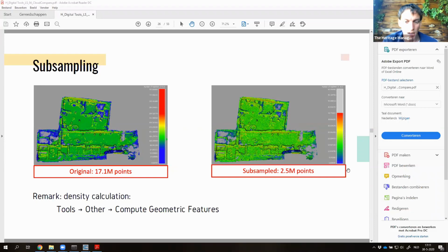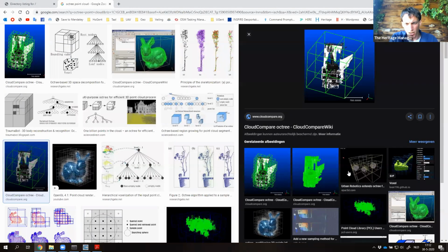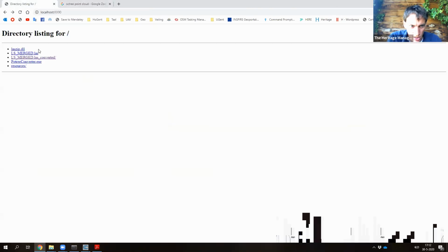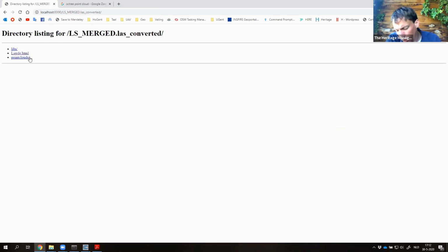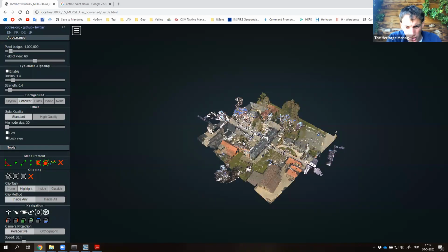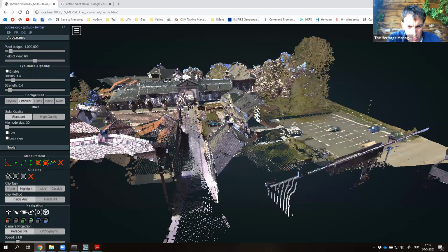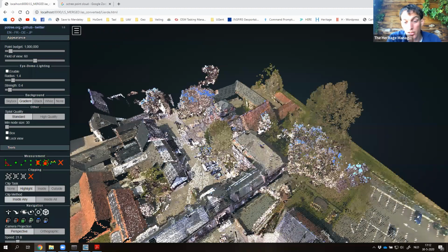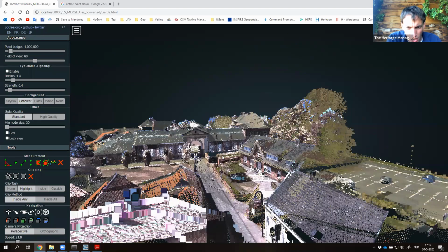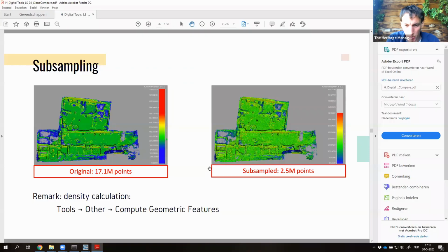I assume that Michele, who will do the guest lecture on Monday, will tell you more about this software. So the step from acquiring the data to having your point cloud is something that I will not cover in Cyclone, but I think we will cover that on Wednesday or Thursday. I will show you how to combine different separated TLS files, and also the cleaning of the data, registration of the data, and visualization in online environments. Something similar to what we did with the panoramic viewers, you will also be able to generate something like this. Here we are looking at many millions of points. It's just pre-processed data, a combination of the airborne laser scan data and terrestrial laser scan data in a web-based viewer. So those are things that we will cover in the coming days.